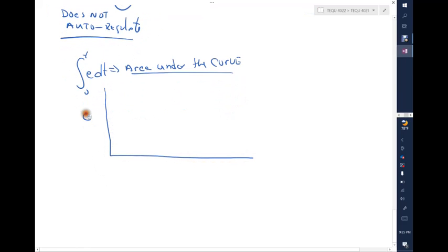You have the error here and you have time here. At time 0, you always have an error, like set point minus PV always produces an error, right? So you have a number here. For the timing, let's say that's 5. And 10 seconds later, because that's our delta t, that error increases, let's say, to 10. So we are here. Now, 10 seconds later, that's 20. And let's do this 20, 30, up to 40. And there it dropped from here to 0.